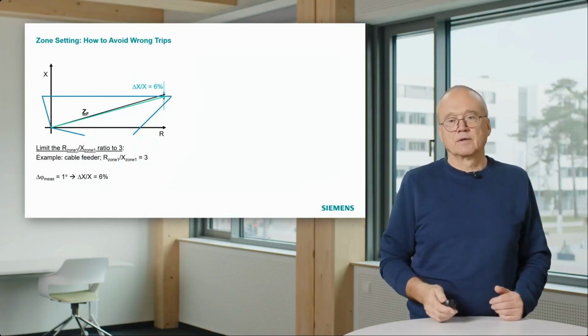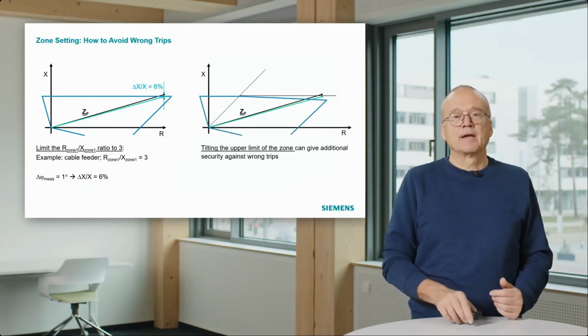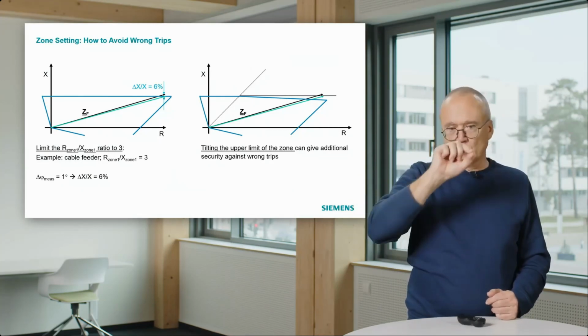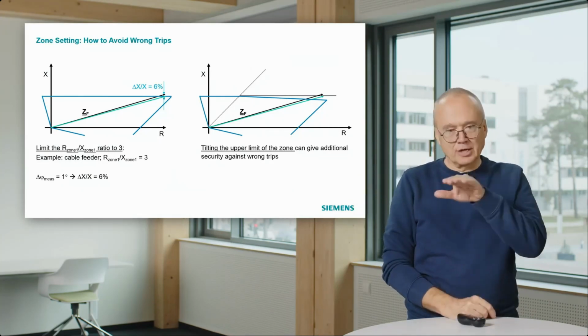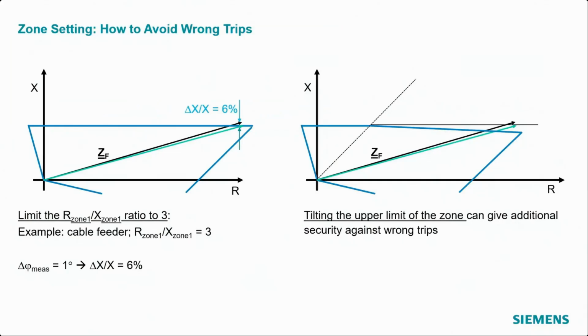And now what does the slope give us? If we set a slope here, we start the slope at the point where the zone limit crosses the line characteristic. Then you see, the bigger the fault resistance is, the more we take the reach back.